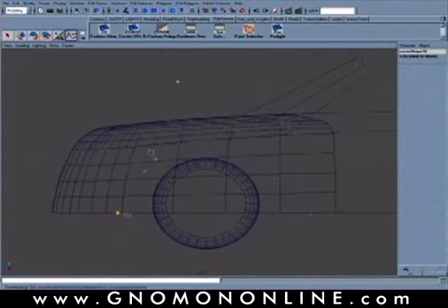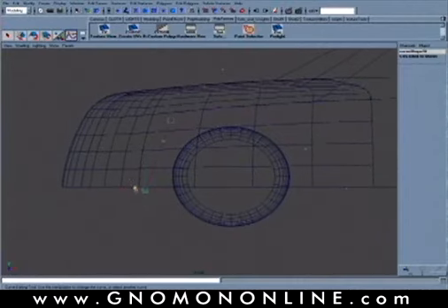Now, if you're unfamiliar with this tool, basically the way it's set up is this diamond, the yellow diamond that I have selected now, will allow you to translate across different parts of the curve. And if I move it all the way down to the end, then you may want to take advantage of the little jack lines that are showing here in green and red to create kind of a snapping direction. If you're all the way down to the end, it will only modify that next CV from the end of the curve. Meaning that if I want to snap this line to the y-axis, it will make sure that only that next CV is aligned there.